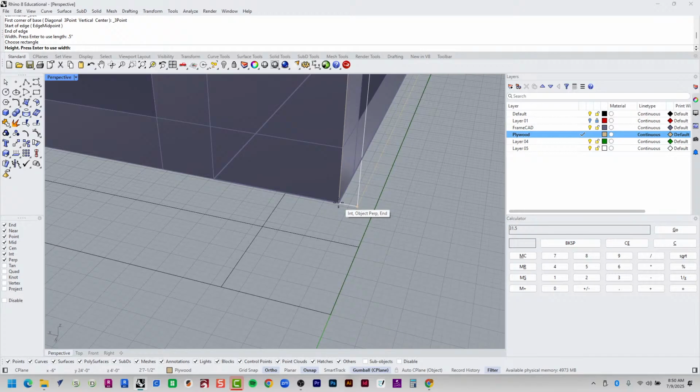Now the frame CAD, we don't want to see it. It's so ugly. The caster wheels, we don't want to see those either. They're so ugly, right? We want to see the beautiful plywood. So when I snap to this endpoint, if you look down in the bottom left of the status bar, just down here, as I snap to that endpoint, it says 2 foot 7.5 inches, which is 31.5 inches.